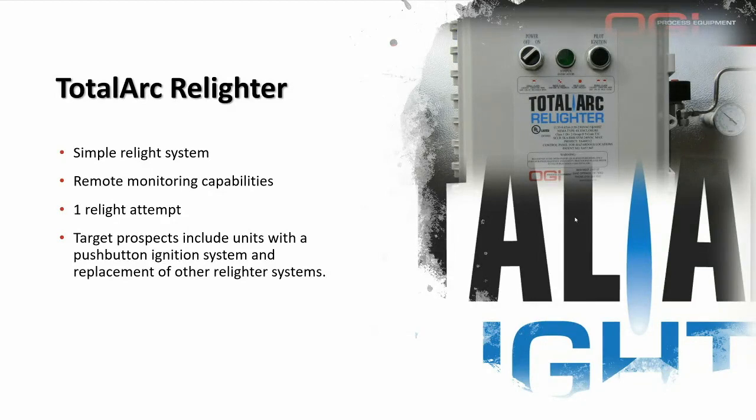We didn't want to add another layer of complexity for those customers that like to maintain that simple approach. Even with the simplicity of it, we still include remote monitoring capabilities, and truly this is just a dry contact set that, in the event of a complete flame failure, will send a signal out indicating that your heater is down.